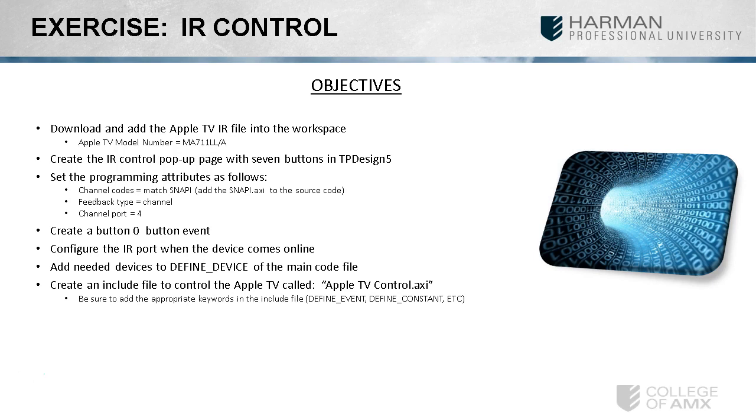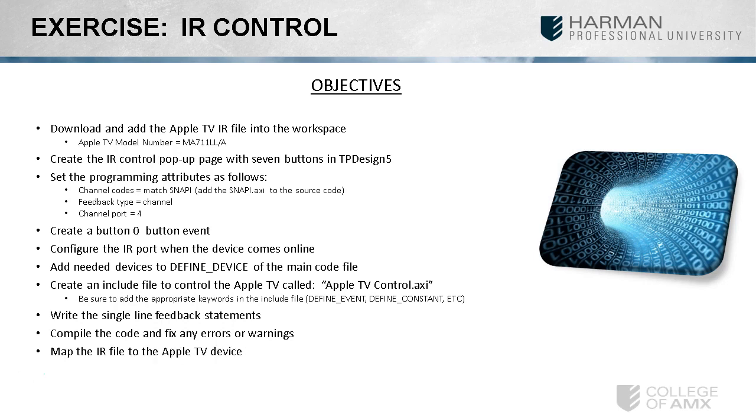Also, be sure to add single-line feedback so that the buttons on the touch panel provide a visual confirmation to the end user after the button was pushed. Make sure your code compiles without any errors or warnings. Finally, map the IR file to the appropriate device in your code.